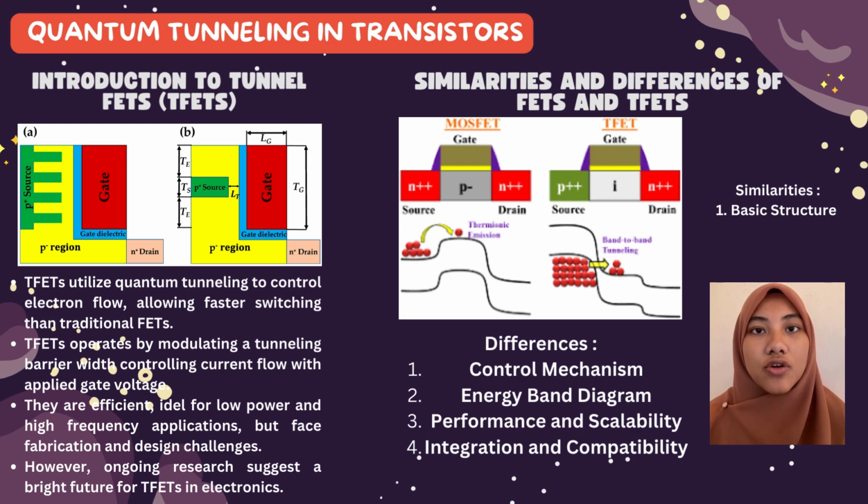Lastly, integration and compatibility. Some TFET architectures, like line TFETs, are designed to be CMOS compatible and easy to integrate using standard CMOS unit process steps. This compatibility is essential for transitioning from traditional MOSFET-based technologies to TFETs in a gradual and seamless manner.